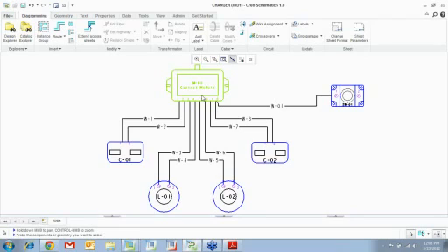Now we would take this diagram and export it as an XML file, and we will import this XML file into the cabling package into Creo Parametric, and then route the cables. Now, there are two important things that we need to be careful about. Now, first thing is, how are we going to map this particular symbol to a component in Pro Engineer, or I'm so sorry, Creo. So how are we going to map this symbol to Creo?